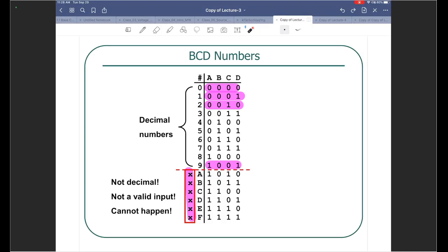So that has to be determined by the problem statement, or a few statements that denote what that digital design is about. For example, here, the BCD numbers are only from 0 through 9. 10 to 15, hence, are don't cares with a 4-bit combination.